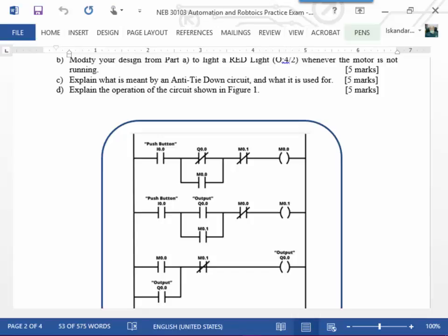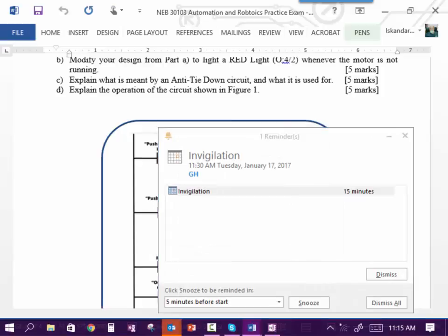So if your hand is in there, it's going to see 400 kilograms per square centimeter type pressure. It's a lot of pressure. So if your hand is in the press, your hand disappears. And I am very intimate with anti-tie down devices because I've seen people lose hands. I used to work in a company that made clutch facings and gears and things like that, and tires, and we had this type of equipment. And I've seen people that actually did,